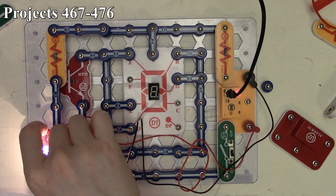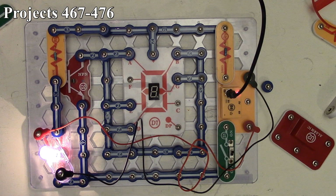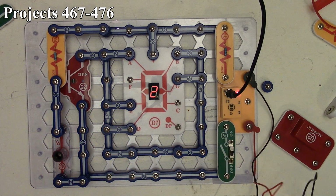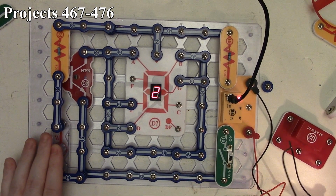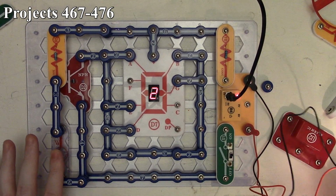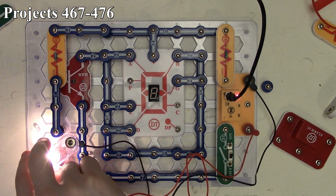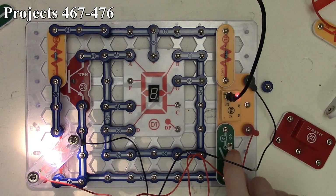And we'll start it like before. We'll put our 6-volt lamp over that, turn the circuit on. Again, nothing should happen because we got so much light going into our photoresistor. And as I take it away, number 2 begins to light. And once I cover up the photoresistor, it becomes nice and bright. And again, we got our number 2 showing on our 7-segment LED display. Let some light back in, it gets dimmer. Bring our 6-volt lamp over, and it goes completely out. So that is Project number 468.